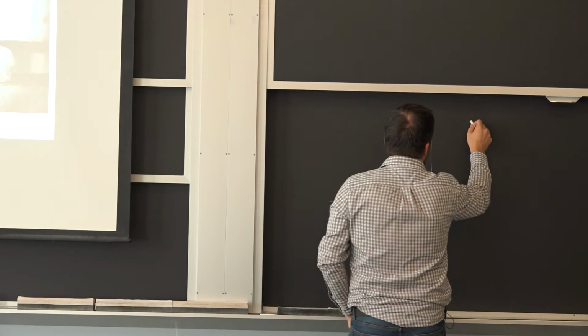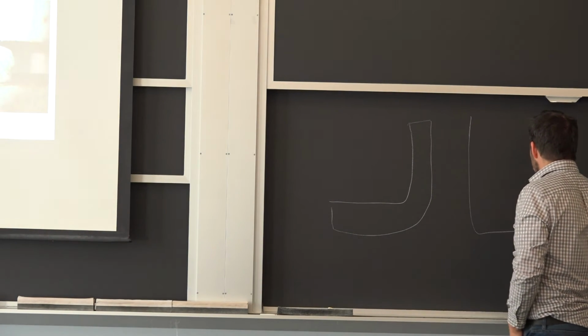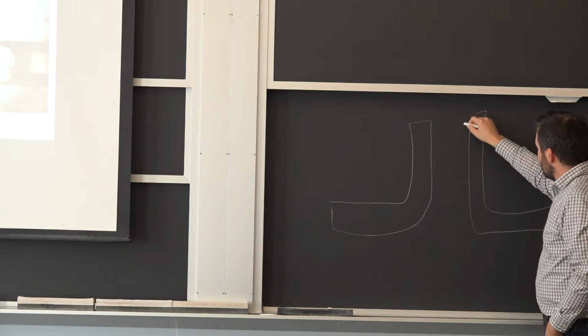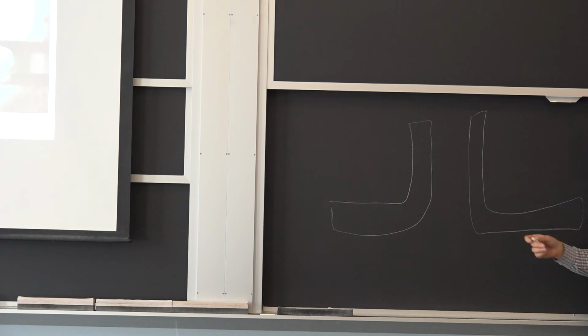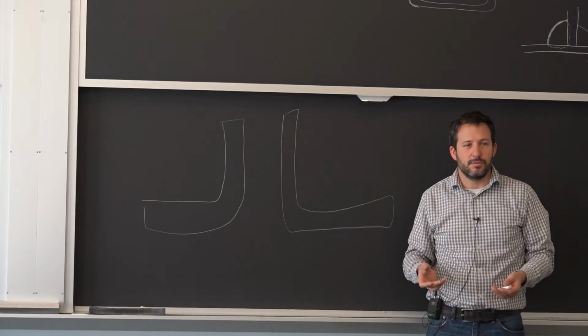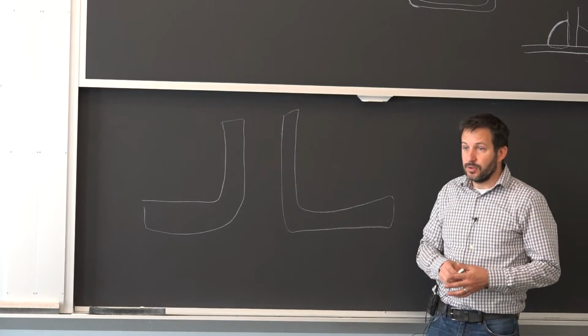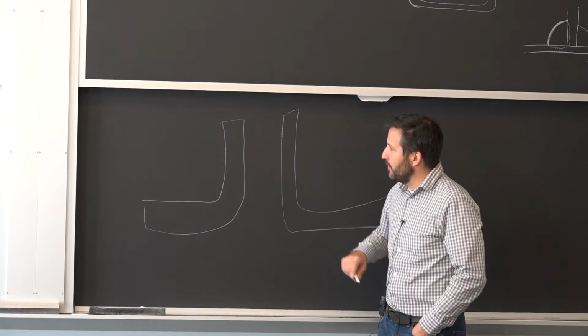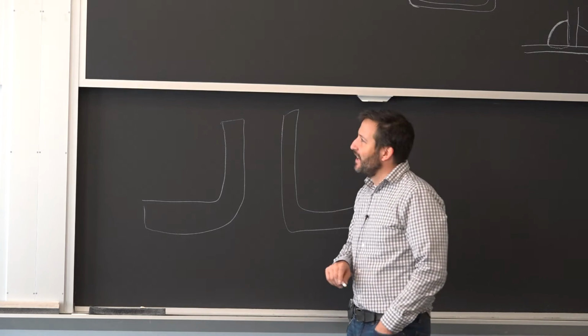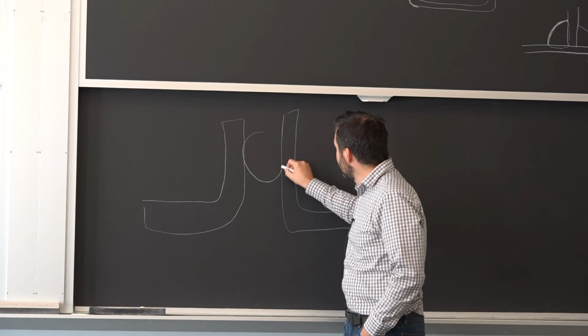You have an angle on one side, you have an angle on the other. These are very cheap to make. It's just by rolling. You don't need to do an extrusion, or a drawing to make an empty tube. So by weight, it's a lot cheaper, and then you try to fit the diagonal in between. So let's say you put it there.